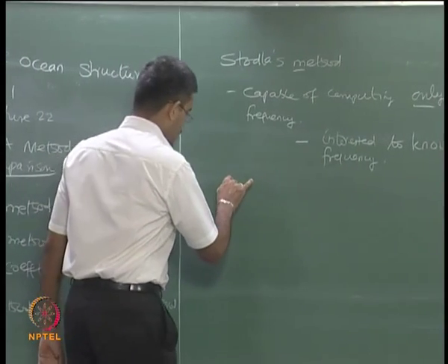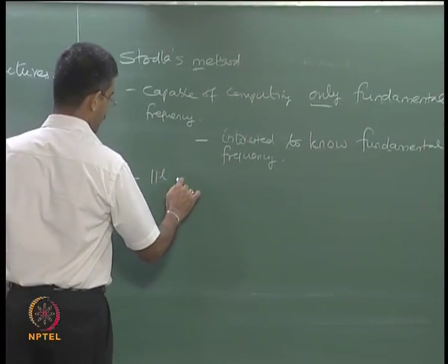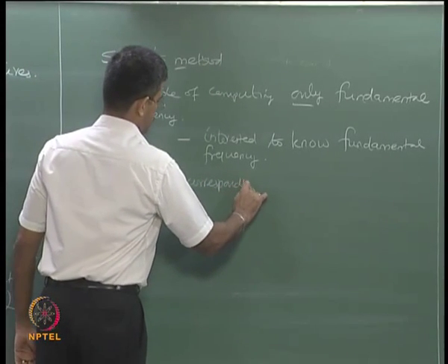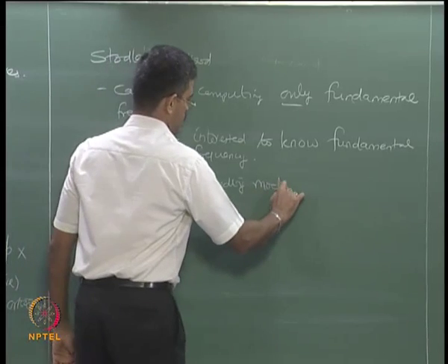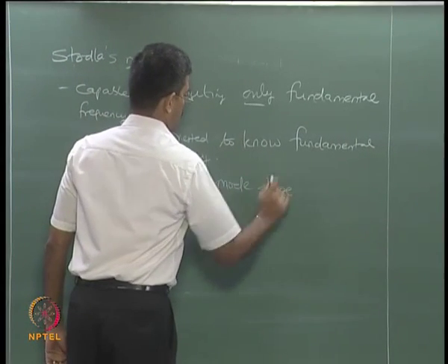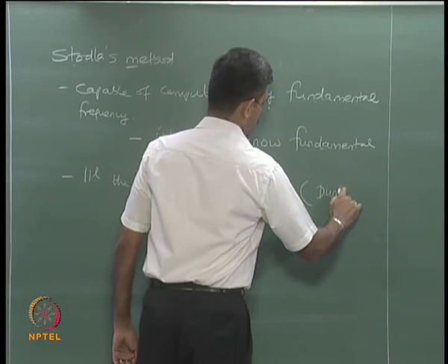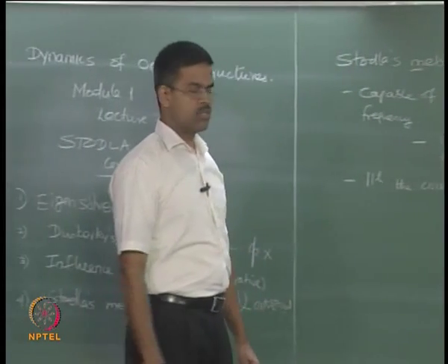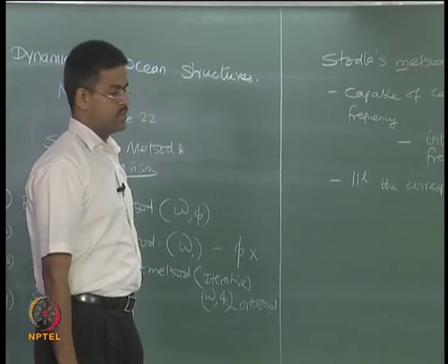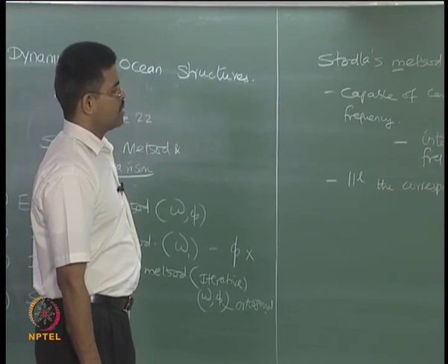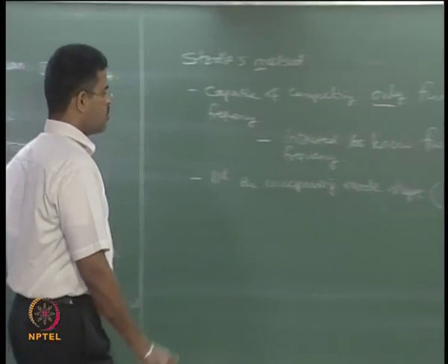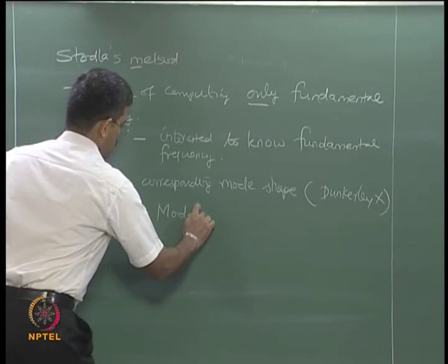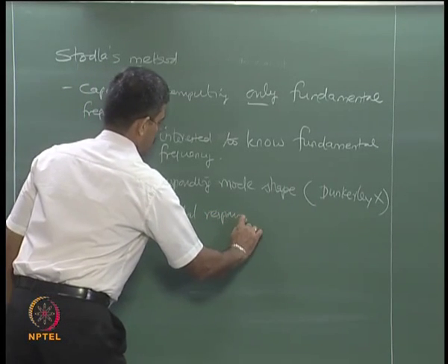This method also gives me parallelly the corresponding mode shape, which Dunkerley could not give. This method gives me also the parallel mode shape associated to this frequency. So if I know the mode shape, the great advantage is I can do what is called modal response analysis.